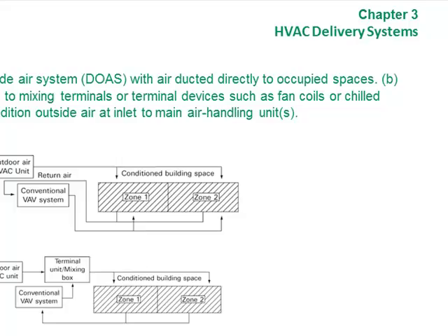Well, the difference in the two of them is that the 4-pipe fan coil system over the 2-pipe fan coil system, the 4-pipe is more flexible. Right, it's more flexible because it can run hot and cold at the same time. Two pipe can only do hot or cold. So if you wanted a more flexible system, you'd recommend the extra construction costs for the Cadillac. What's wrong with Honda?